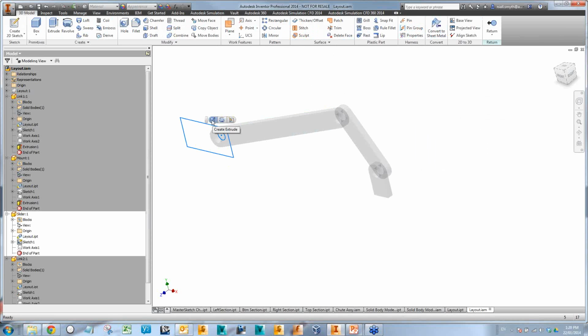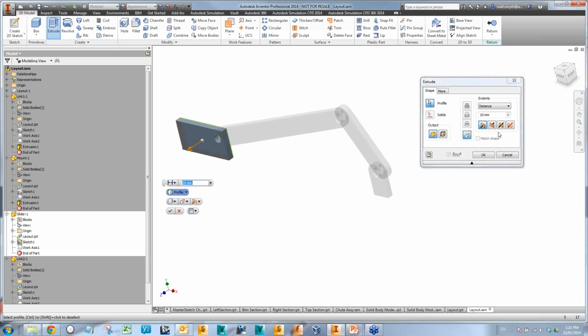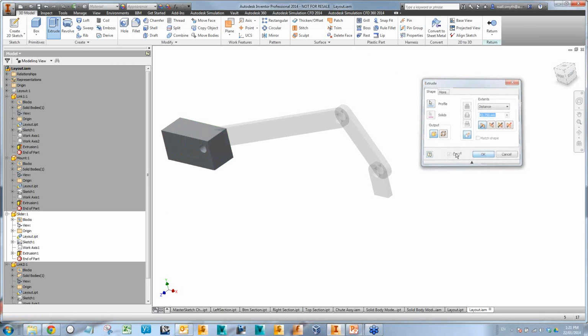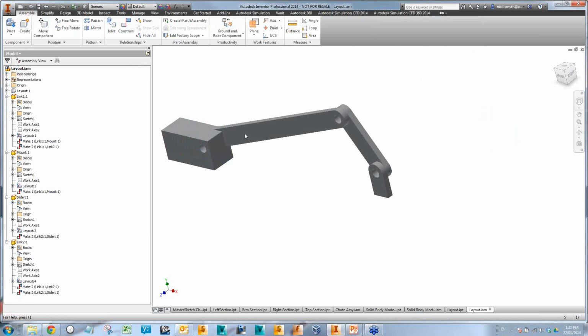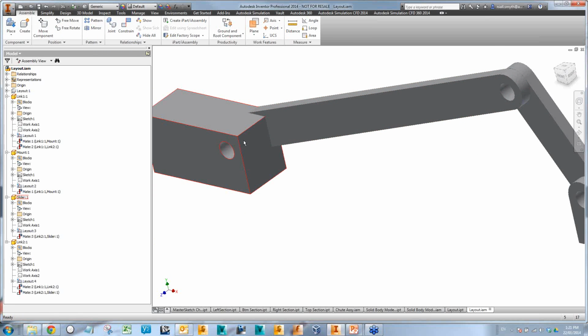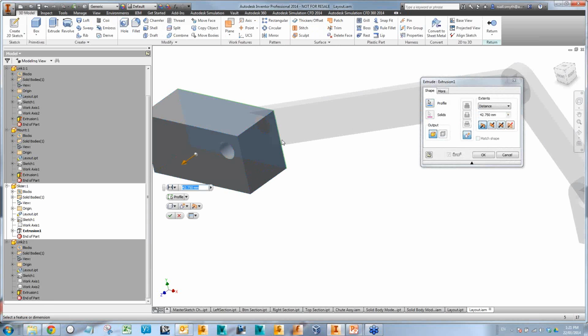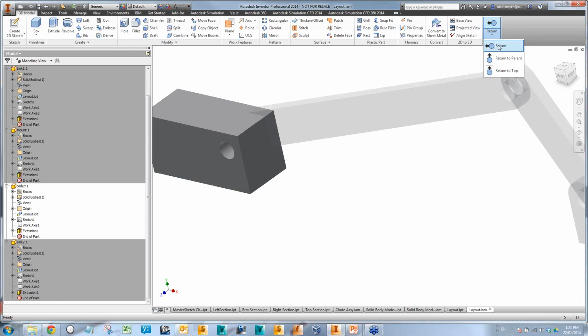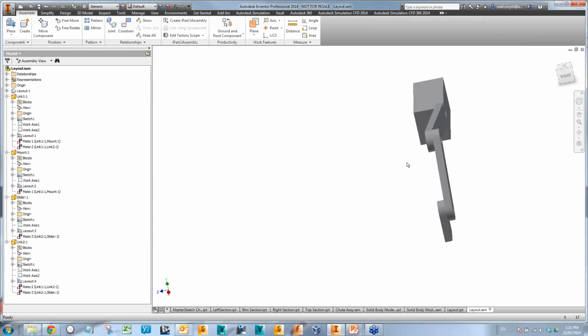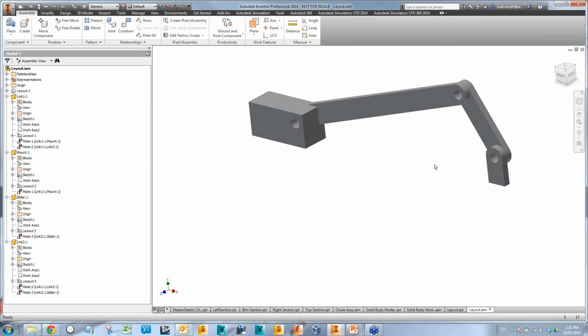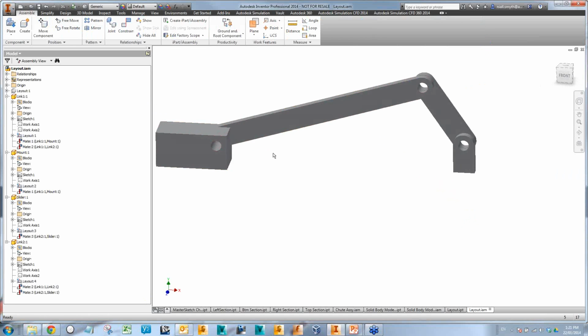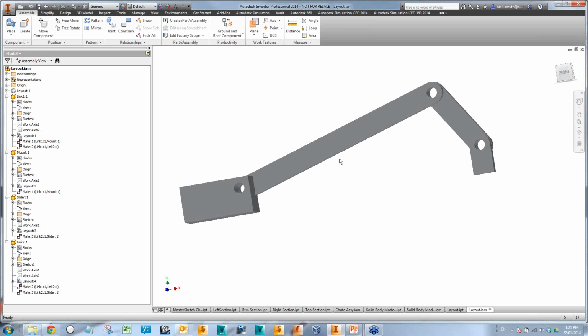And the quick access toolbar, you see there when I click on a line, it comes up with the extrude option, which is really handy. So, whoops, I think I've extruded that in the wrong direction. So let's go back and, I think there's a little bit of interference in the directions, so I'd need to go back and modify that if I have started extruding in the wrong direction. But I think you get the idea of what I was trying to do. And you can see you can actually extrude the parts that we're working with. So that's layout design in a nutshell.